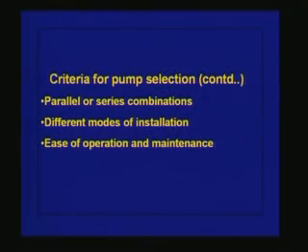Then other important considerations in the pump selection are what are the different modes of installation, how are we going to install these pumps, what kind of space is available for us in the pumping station to install these pumps, how we are going to move the equipment and so on and so forth. That is also an important consideration in the selection of the pump.